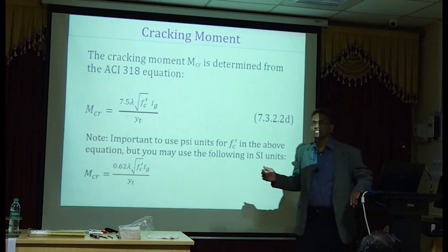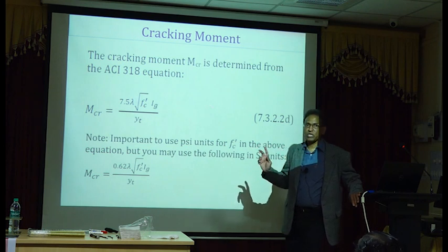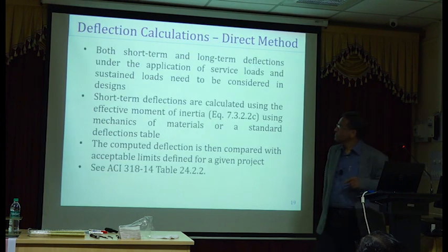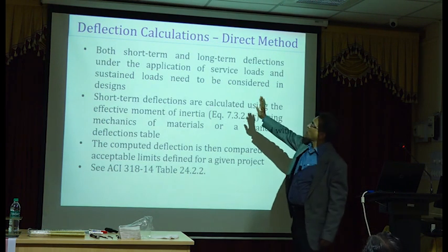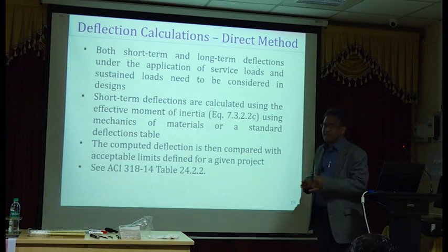I sub G is the moment of inertia of the uncracked section, which is the gross section without any cracks. So we need to find both short-term and long-term deflections based on this method, and you apply service loads.